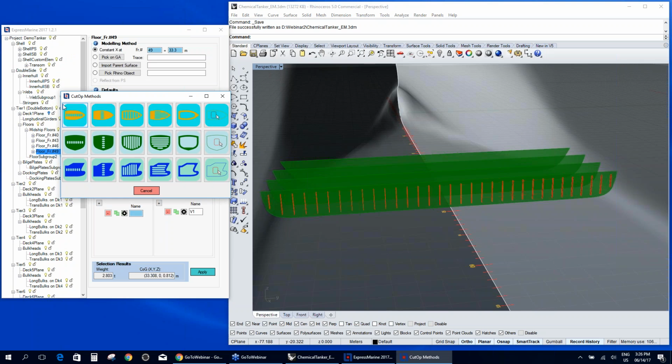We can have series of repetitive shapes of openings, or we can have openings that repeat in a certain direction, but with the height adapting to the contour of the element, or you can have a parametric offset where you offset all the edges of a certain element, or if we have some shapes defined already in the drawings, we can select those closed curves, and that shape will be then punched into the object.